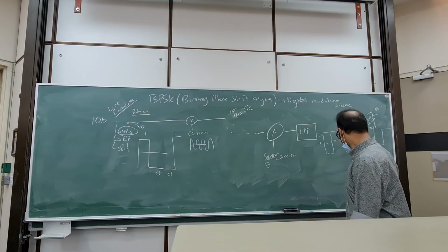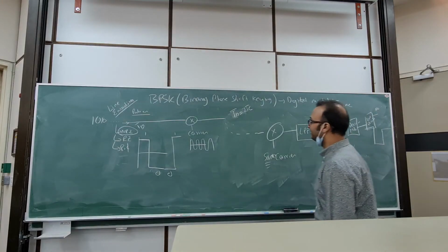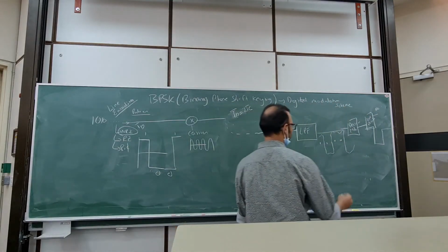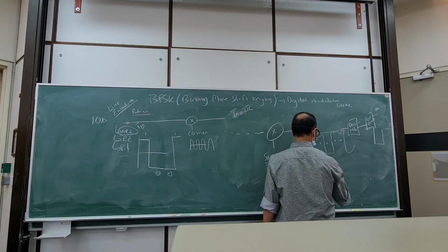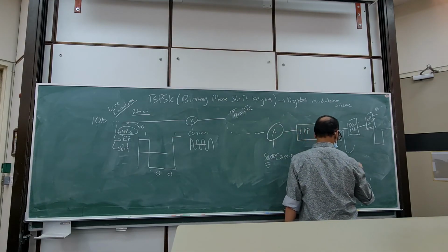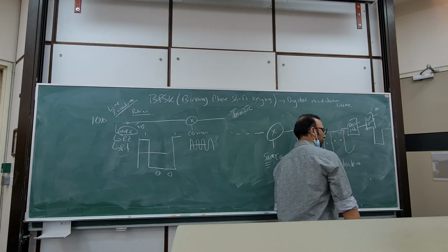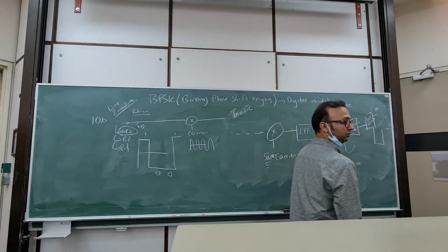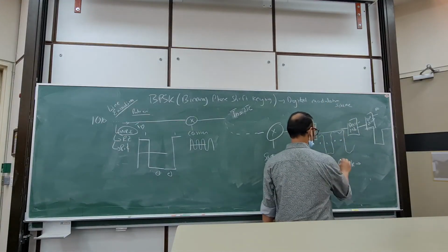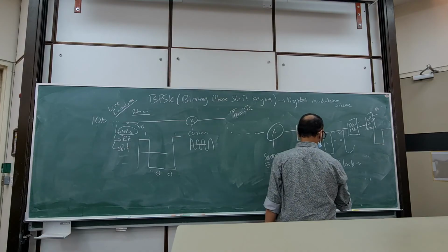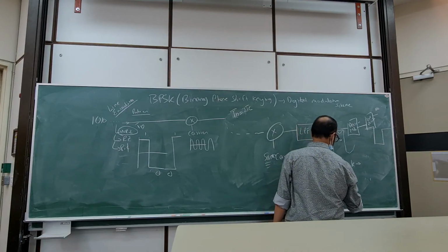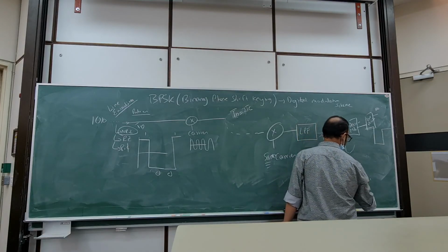One important problem that all of you will face is bit clock and master clock. You use the same bit clock throughout, and you get the bit clock from the line encoder.